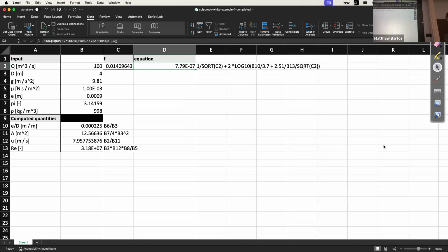Okay, so I have a fix. For some computers, for some reason, the solver doesn't respect the constraints that we give it. To fix that issue, we need to modify this formula to make sure that the value for C2 that's going in for the friction factor can't ever be negative or 0. So I'm going to take this value F and modify it slightly.